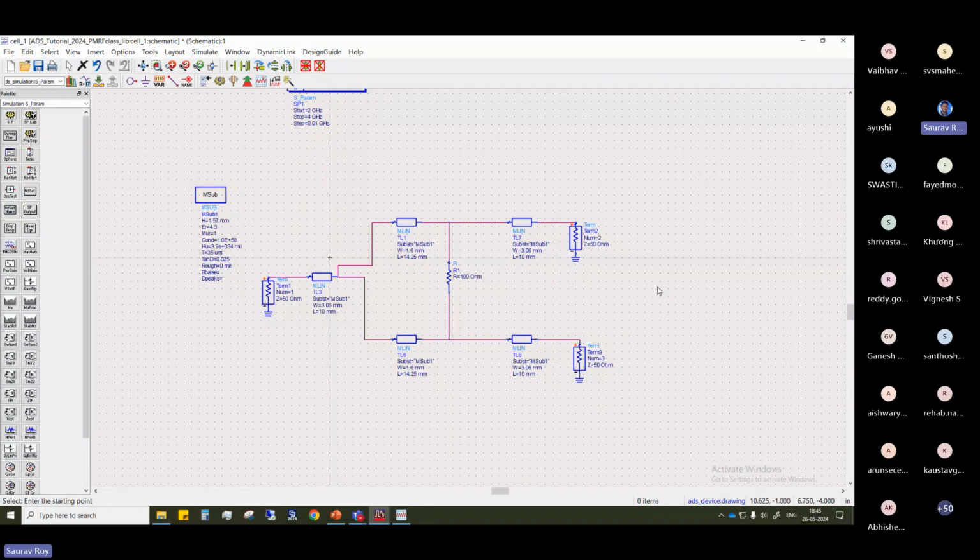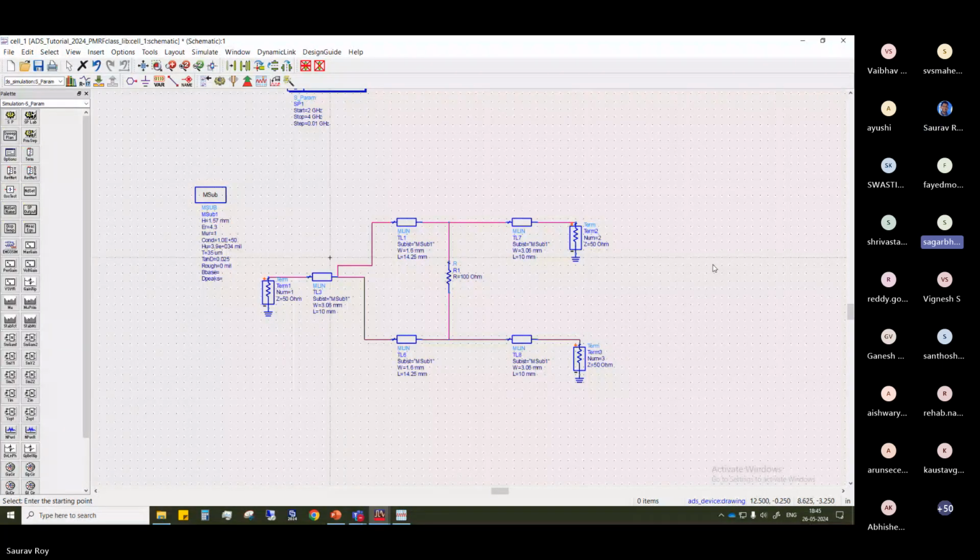Sir, here we are designing the microstrip line above the substrate, right? Yes. For example, if I have a unit cell and on top of that substrate I have created a patch, now I need some kind of power dividing or power coupling beneath the substrate at the bottom layer through microstrip lines only, matched to 50 ohm. Below that microstrip line is an air spacer, let's take it about 12 or 14 millimeter.